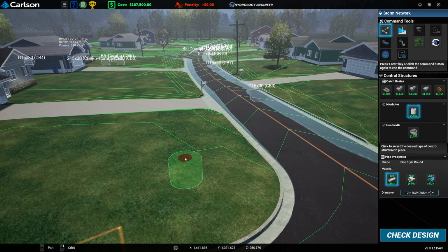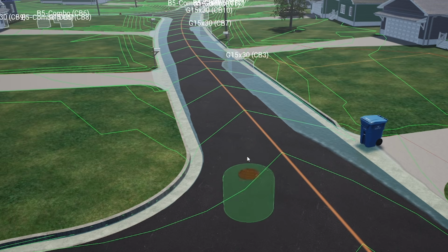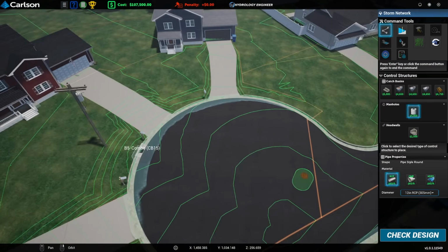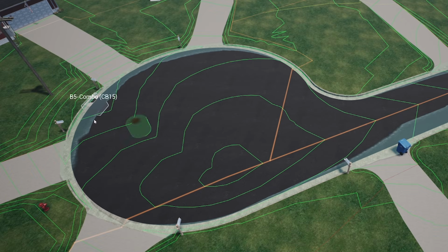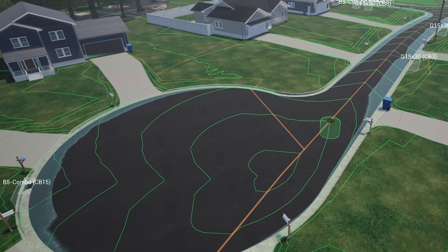So generally you can go down to about, I think it was 600 mil cover in a field if there's not going to be any traffic on it. 1.2 meters depth in a road, and that's to the top of the pipe, like the cover of the pipe. Also worth noticing, we generally go 30 meters from a gully to a manhole. That just allows us to clean from the gully to the manhole quite easily. If it's longer than that, it gets quite tricky.